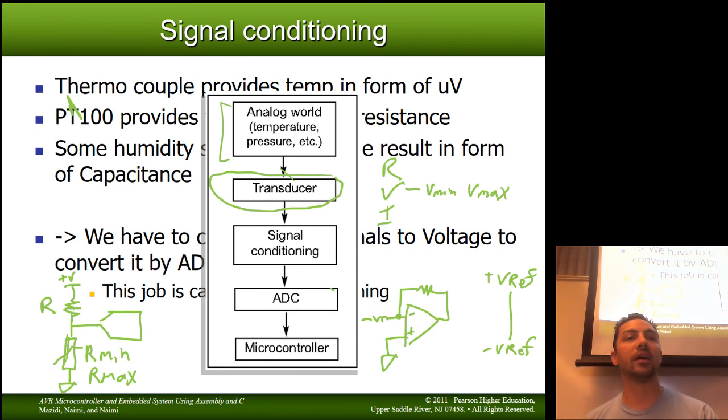What is this circuit? It is an op-amp in a particular kind of configuration, an inverting amplifier. It amplifies the signal by some ratio, RF over RN, or however you want to label it. You might also do a non-inverting amplifier, depending on what kind of value you need.